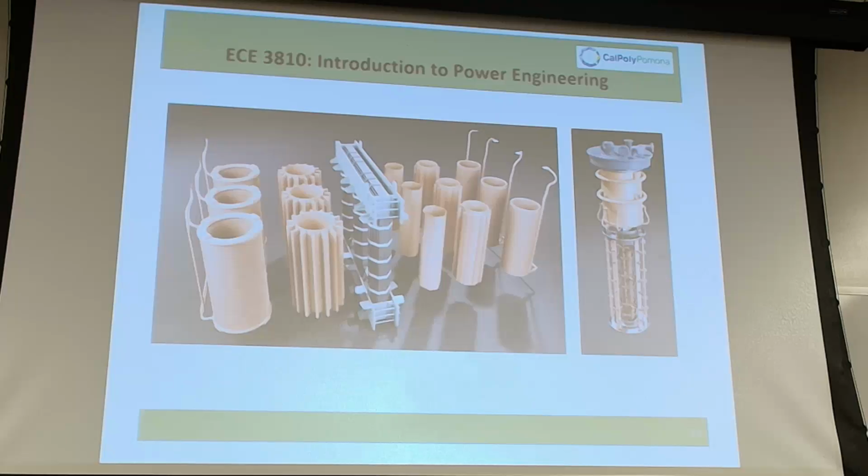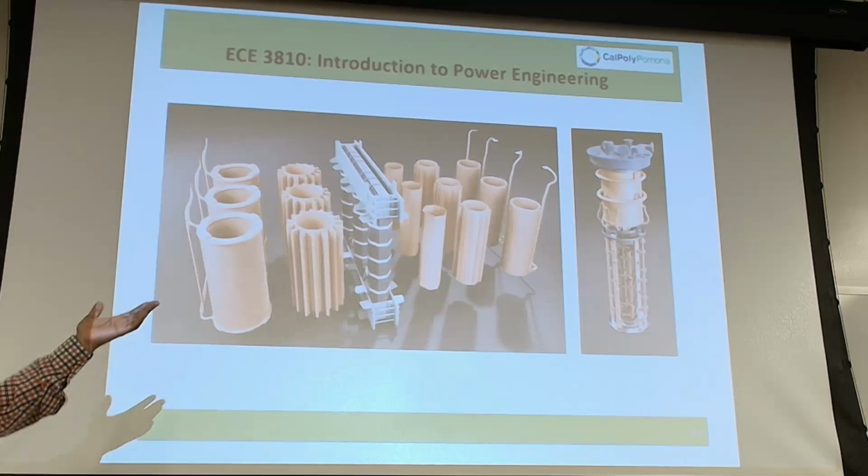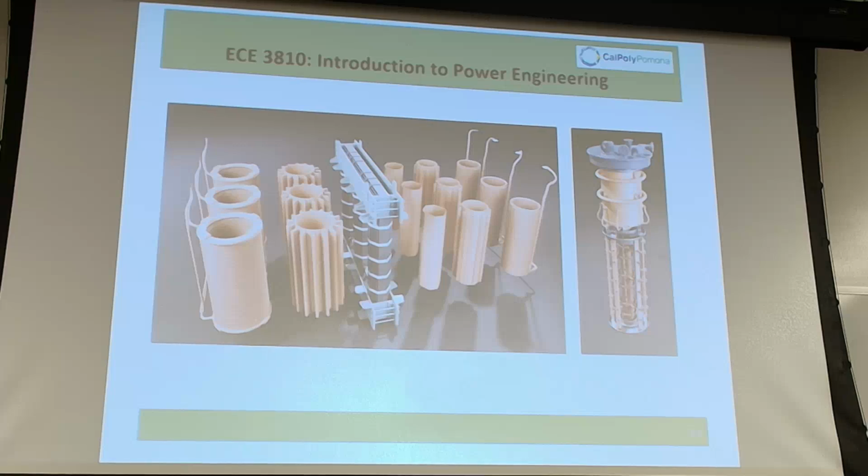So that's really the only active control that you can have. Say that again? That's the only active control you can have with this. Yes, that's the only active piece. That's the piece that actually moves unless you have pumps, right? But yes. And I'm talking about large transformers. Small transformers don't have tap changers. Too expensive to have a tap changer.